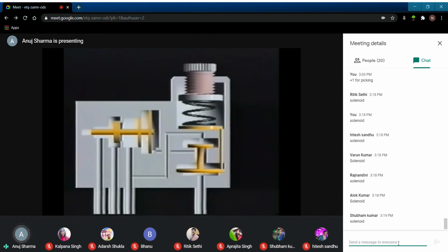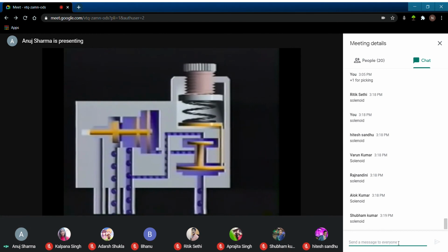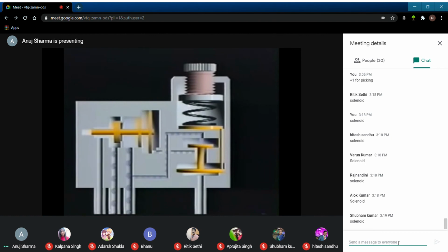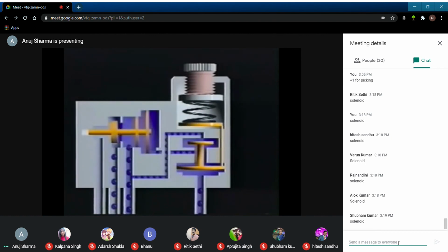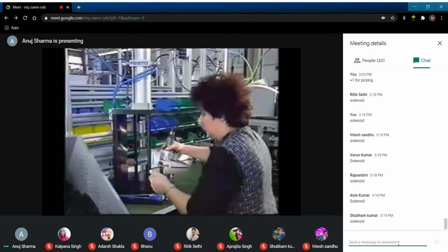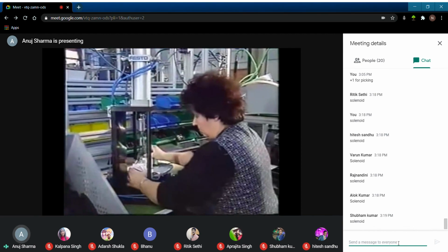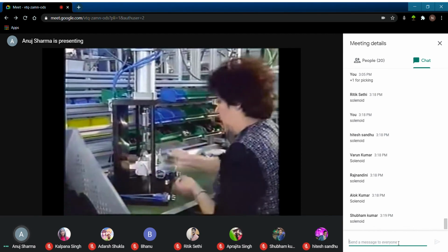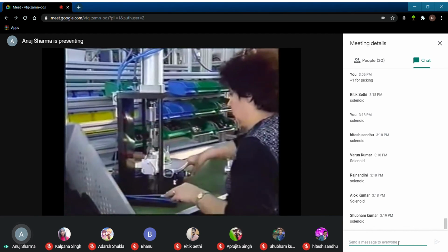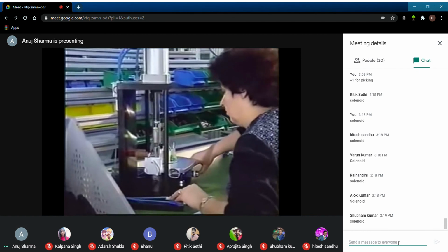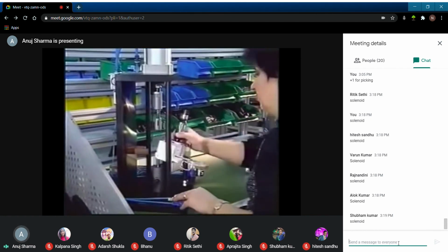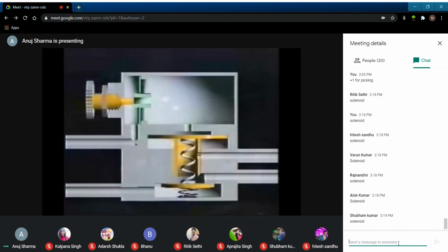One type of combination valve is a sequence valve. This valve switches when a predetermined pressure is reached. In this machine, the sequence valve controls the pressure applied in pressing a shaft into a housing. The pressure valve waits until the shaft reaches the bottom of the hole. When the circuit pressure rises, it sends a signal to retract the cylinder.